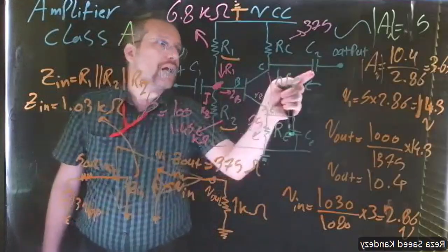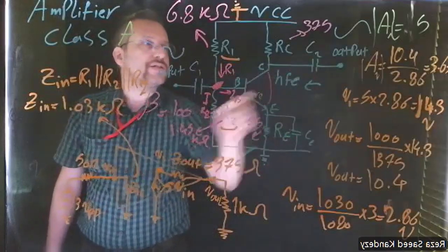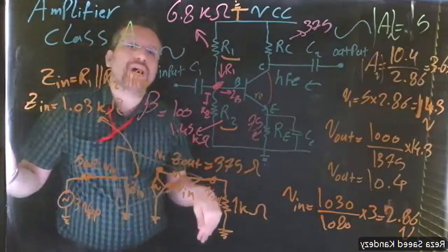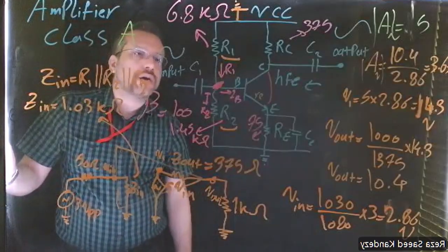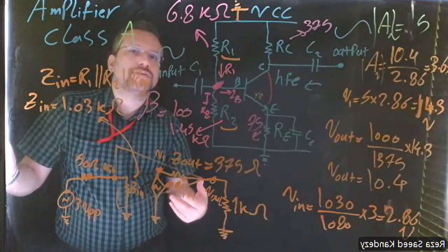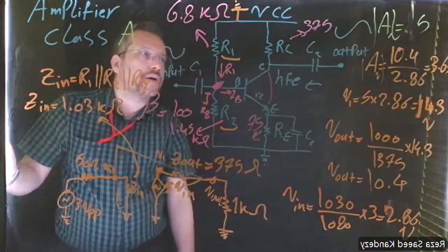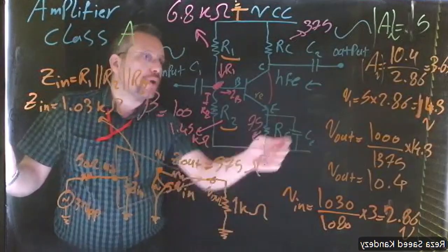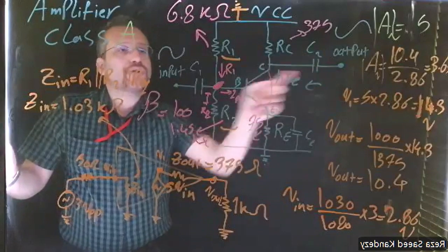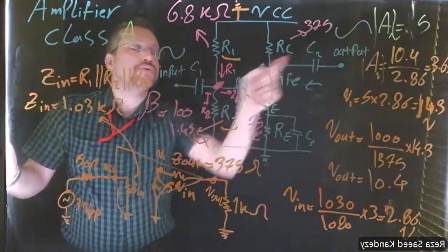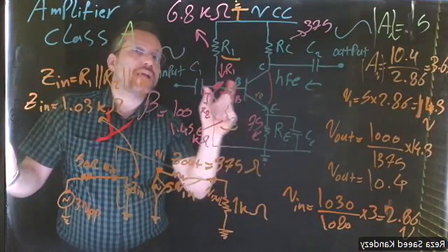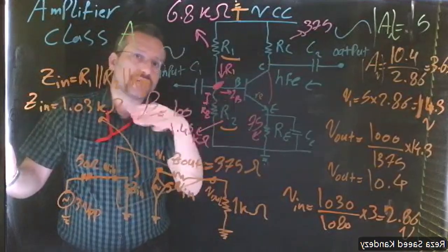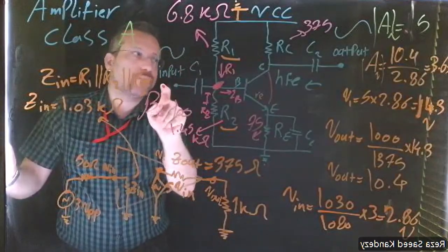Now, we didn't calculate the capacitance here. These capacitors are used, as we said, for blocking the DC. For this specific assignment that you have, you can just pick a large capacitance and put it in your C1 and C2. You don't need to actually do the bypass. If you like, you can do that. But what you use to actually calculate the value of C1 and C2 is the bandwidth that you want, which is the range of frequencies you want to work with in input and output.